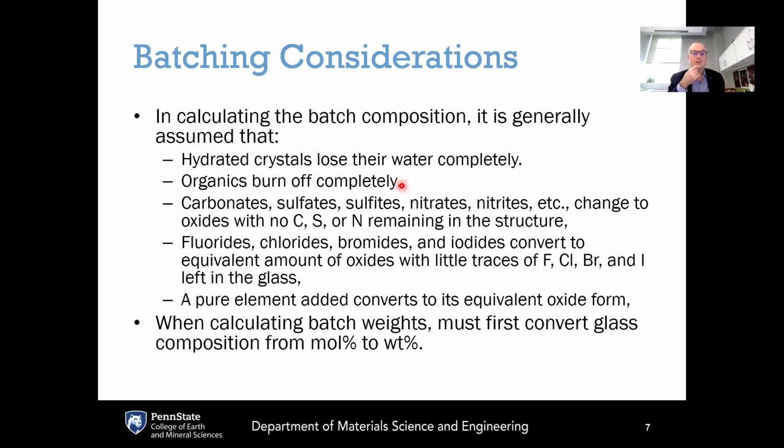So this is especially important if you've got any contamination of your cullet. For example, if any plastics got mistakenly mixed in with your glass, this can be a problem because it's changing the redox state of the glass melter by having these reducing components in there.